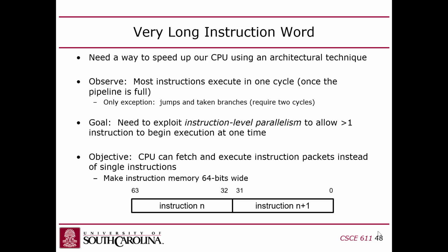So if we're not going to change the number of instructions, meaning we're not going to change the instruction set, because we want to use MIPS, we want to make that standard, make it backwards compatible and all that nice stuff, then there's only two ways, CPI and clock. We can make the clock faster or we can decrease the CPI. So let's decrease the CPI. How do we do that? Execute 2 instructions per clock at most, meaning potentially 1/2 cycle per instruction.